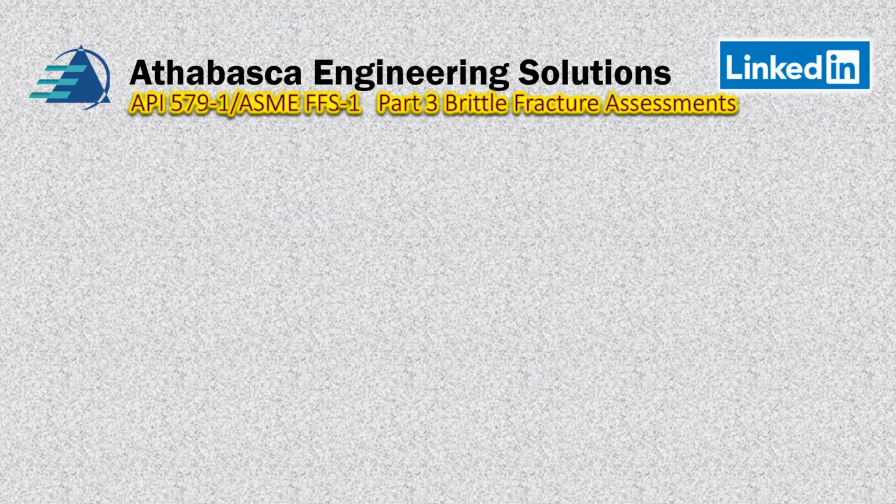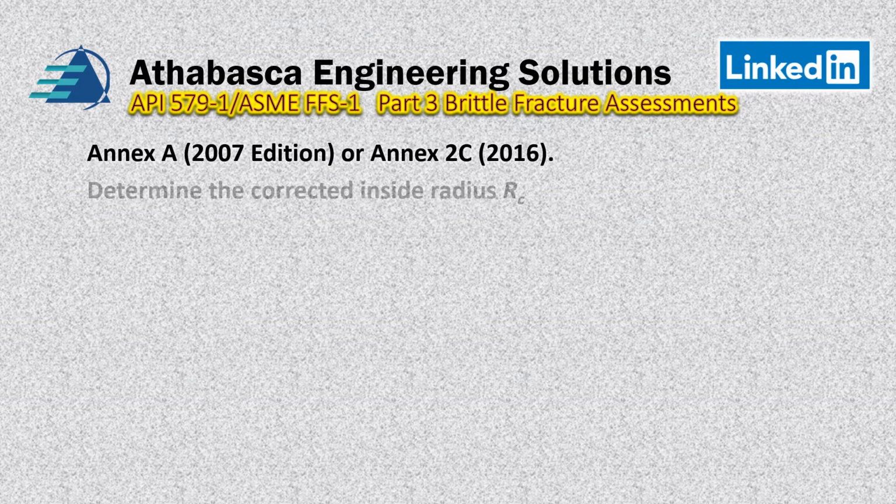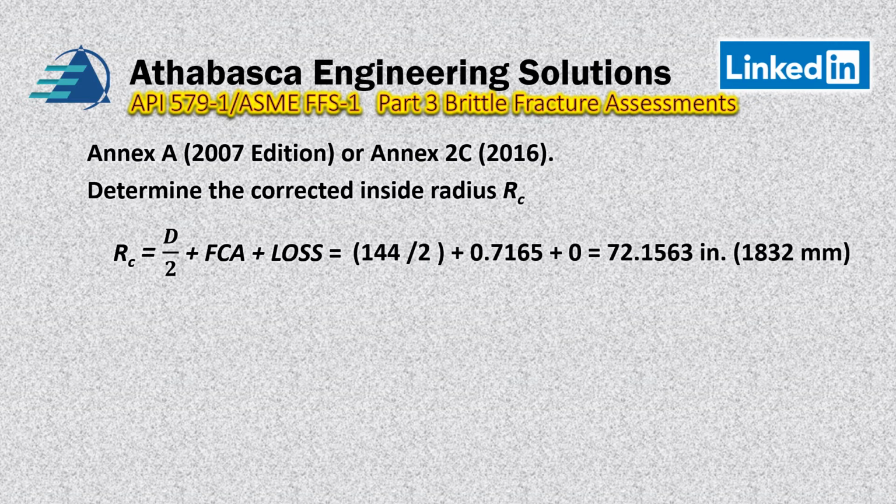The previous example, we're going to have to calculate a couple key items, including the corrected inside radius. We check this, we take half the inside diameter plus the future corrosion allowance plus the corrosion that we've already used up. We do a calculation, we get 72.1563 or 1832 millimeters.